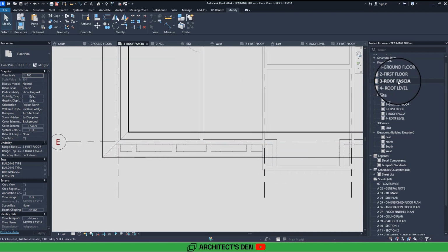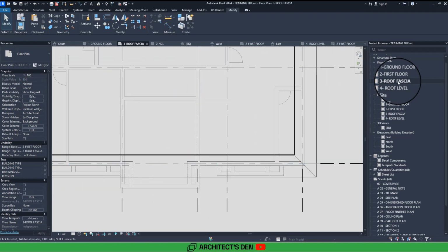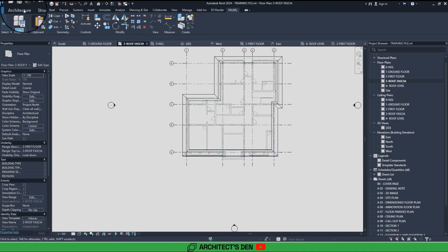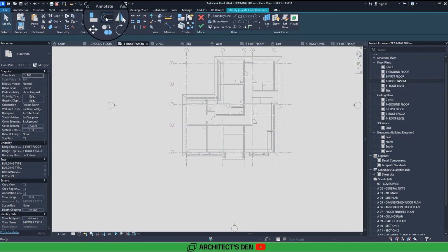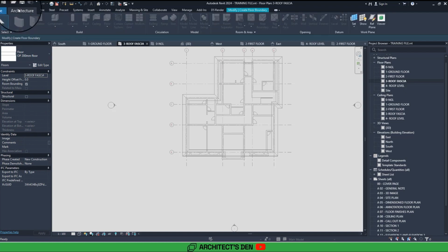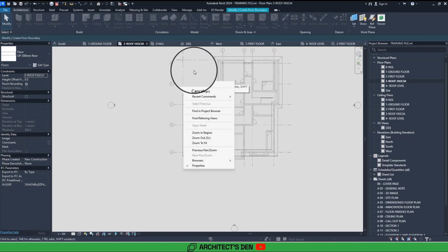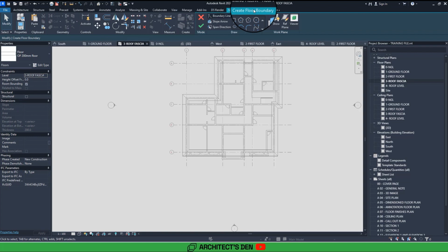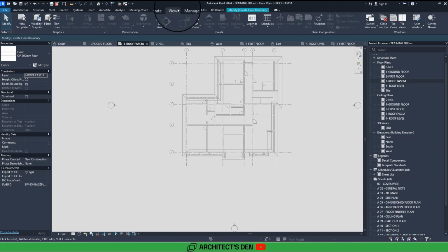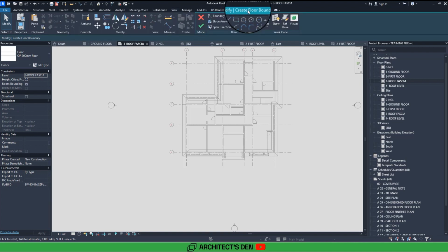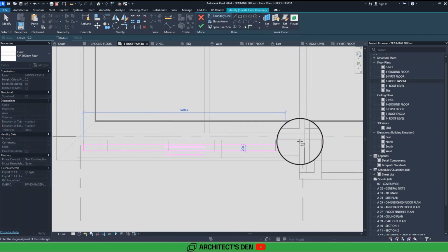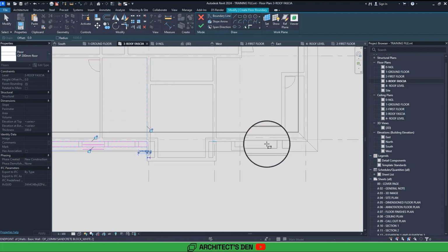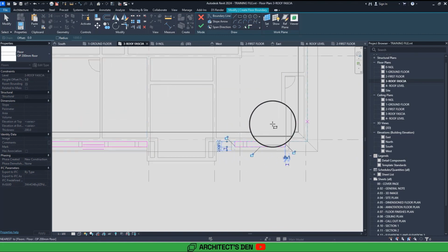And then for these two slabs, this one here and this one here, those are the ones I want to create there. I click on architecture, click on floor. Sometimes you might click on floor to modify it, and things might not work out like this. You just need to come back to this modify, create floor boundary, click on it. I'll click on line. I'll use rectangle now to do that, because I just want to create a rectangular space here and another rectangular space here.